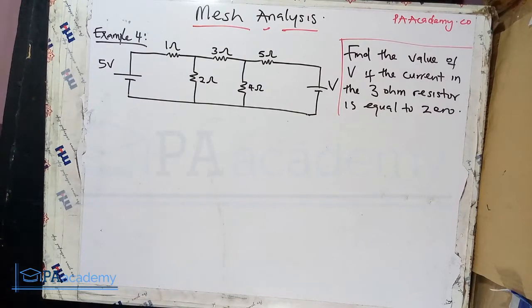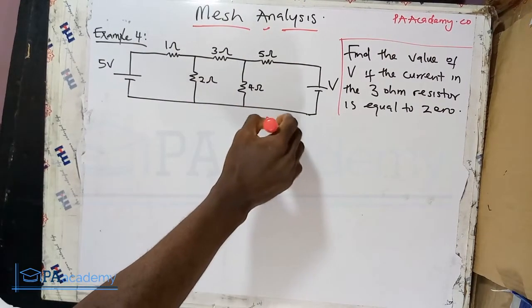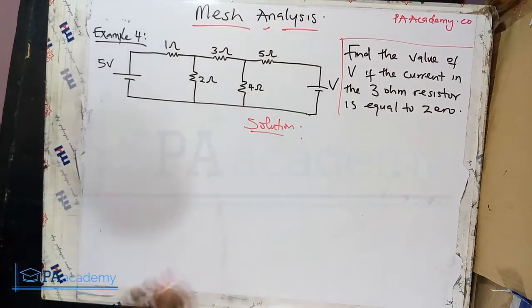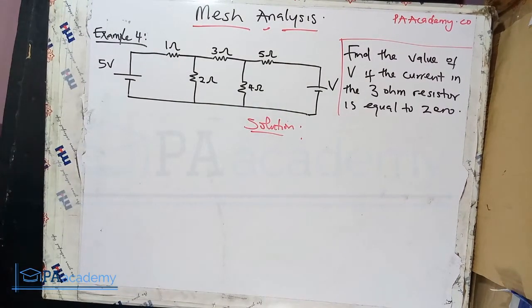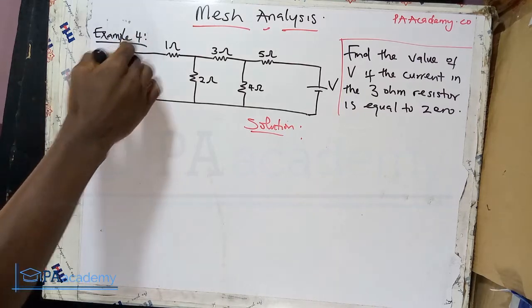So now let's solve this. We are still going to be using mesh analysis, and like I said, if you are dealing with mesh analysis, one of the concepts to use is the Kirchhoff Voltage Law. So we are also going to apply all of the principles I've discussed at the introduction of mesh analysis on how to answer questions under mesh analysis. So the first thing is for us to identify the nodes. So these are the nodes.